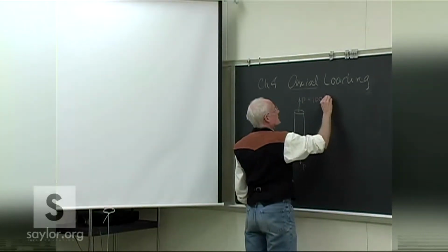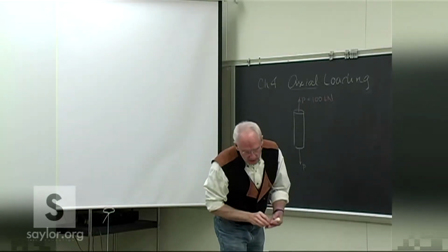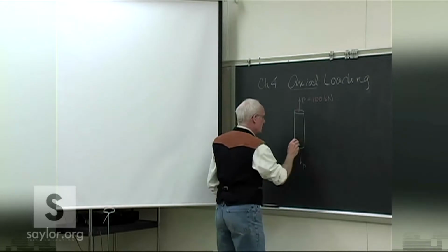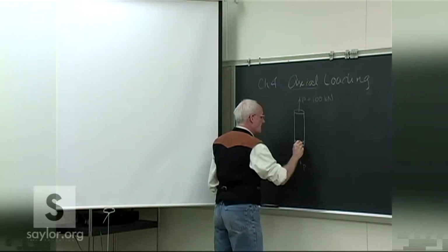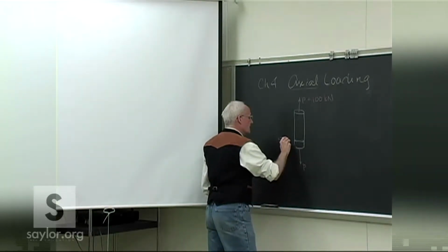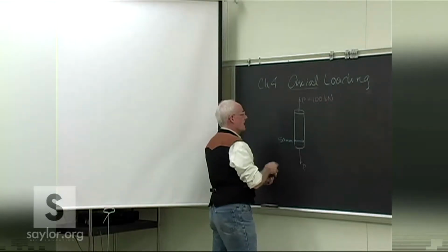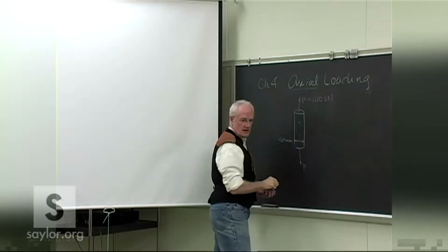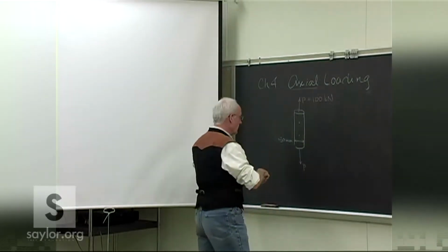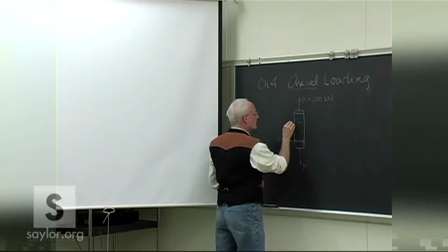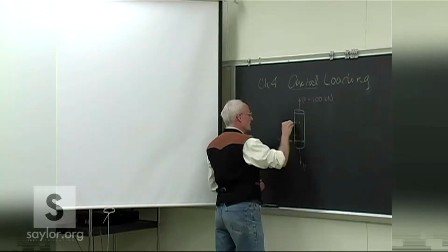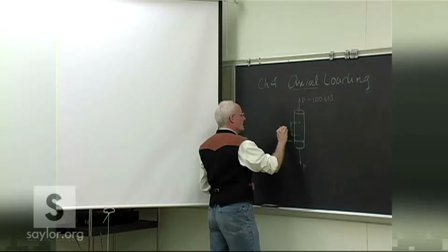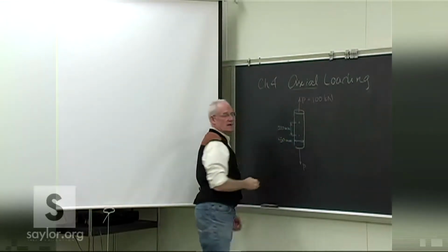So if we have something like that, we'll even put a couple numbers to it just to run through them. Let's say there's a 100 kilonewton load there, and a diameter of 50 millimeters, and a test section in here that will give 300 millimeters. So you can see it's a lot longer in the direction of the load than it is transverse to the load.